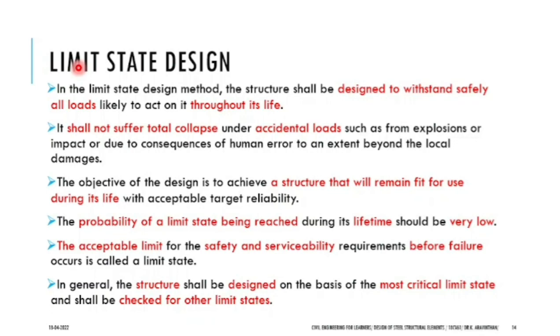Okay, now how to safeguard your structure before collapse? How can you do that? Think. Your structure should not collapse. So what should you do? You should find the capacity of the material. What is M20? If you are making M25 grade concrete, it can take 25 Newton per mm square of stress. So this is the stress carrying capacity.